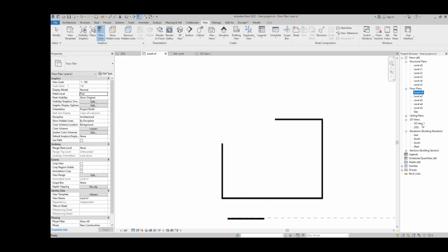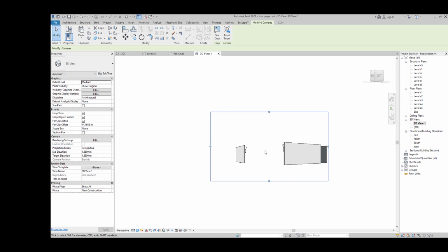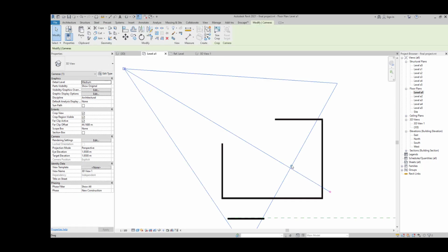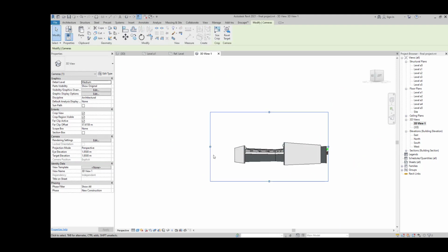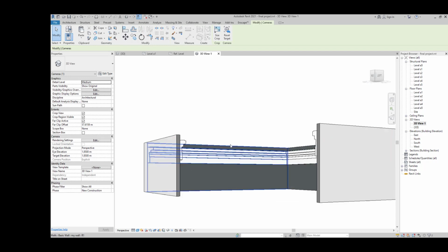Your view is coming in the 3D view category, view, and you are going to have your wall here. You might ask why we don't have the background of our camera. The point is you need to drag this circle so your camera can cover that region here. And we can have this, for example, detail for our project as well with the sweep for designing the classic wall.